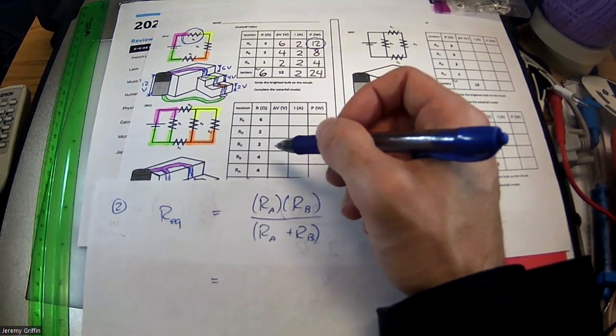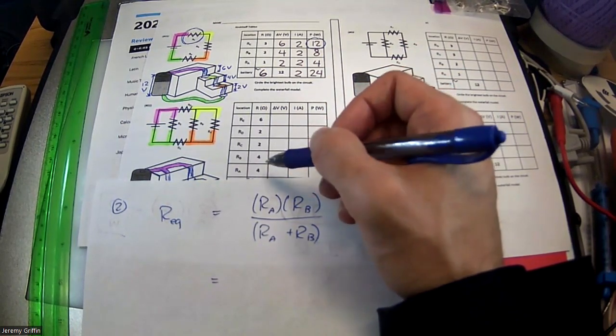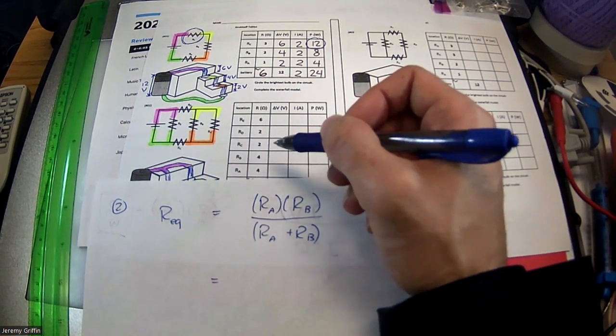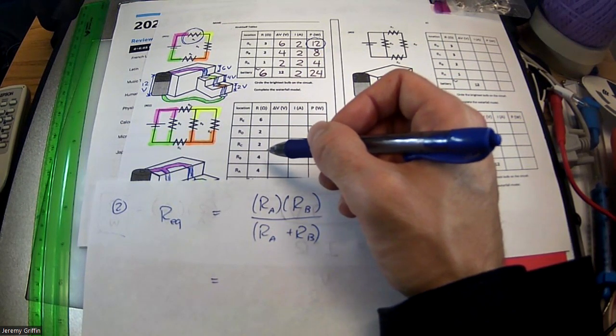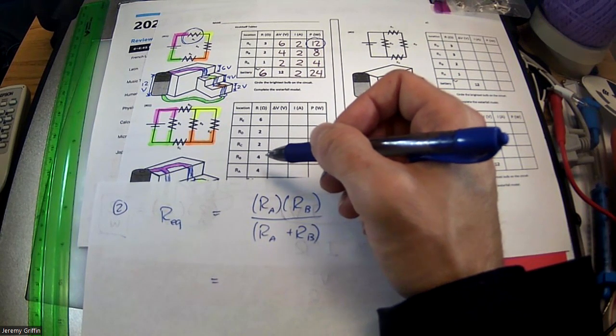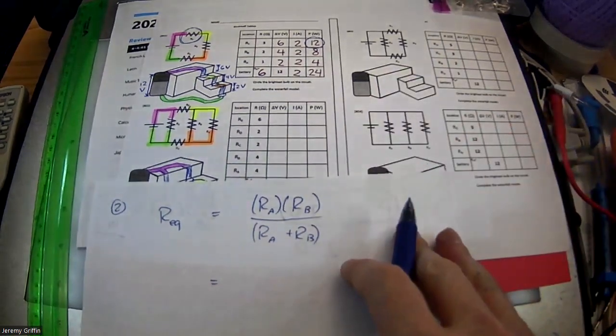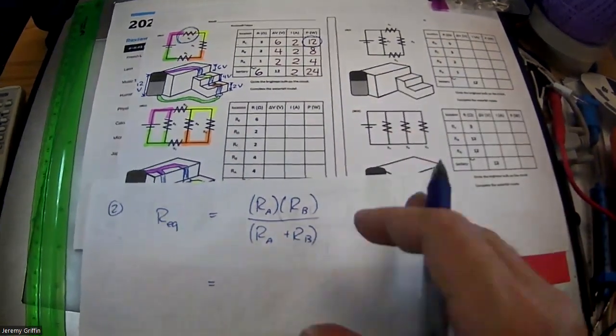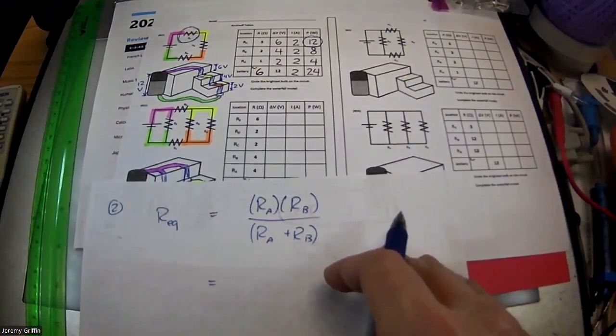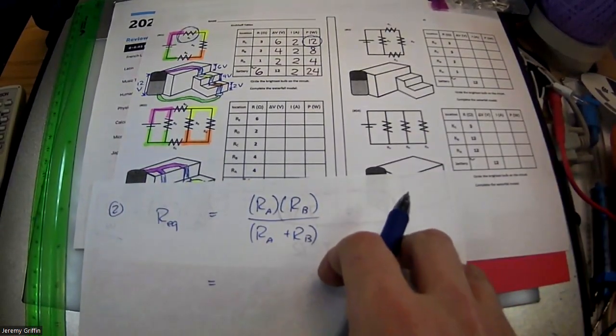Okay. Hey, let's do a painting a fence analogy. If it was 4 hours for this guy to paint a fence, and this guy works at the exact same rate, 4 hours to paint a fence. If they make a 2-man team, how long to paint the fence? Like 2 hours, right? You guys see 2 hours? Okay. I bet the answer to this is going to be 2 ohms. You guys think it's going to be 2 ohms? Okay. That's like a shortcut you can do whenever you have 2 resistors parallel, same resistance each. The total resistance is half of either one of them.